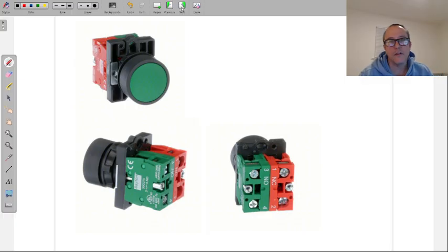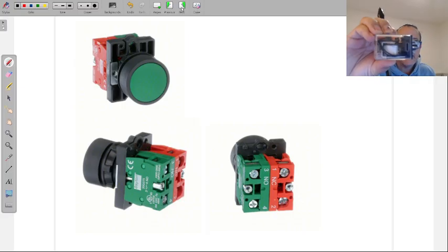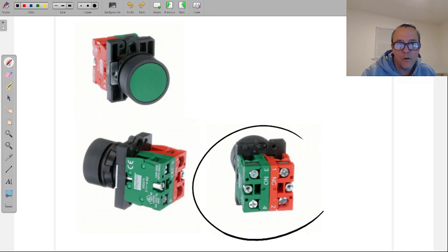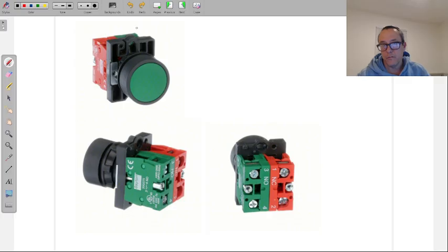And this is especially when you don't have a PLC. One of the things that PLCs do is give you a lot of available internal contacts out of the computer. Whereas if you do not have a PLC running the machine, you need to find physical contacts. You need to put a bunch of relays on the machine's control side. You need to find ways to add normally open, normally closed contacts to the machine to do more functions with. So here's where you see them a lot more.